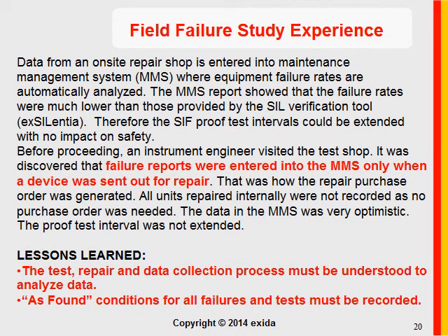But if powering down and powering up, the issue remained, then it was recorded. Well, if powering down and powering up and it works again, that is, of course, a failure of the transmitter that should have been recorded. That is an issue that we should document and take into consideration, maybe an indication of a systematic issue with that transmitter.